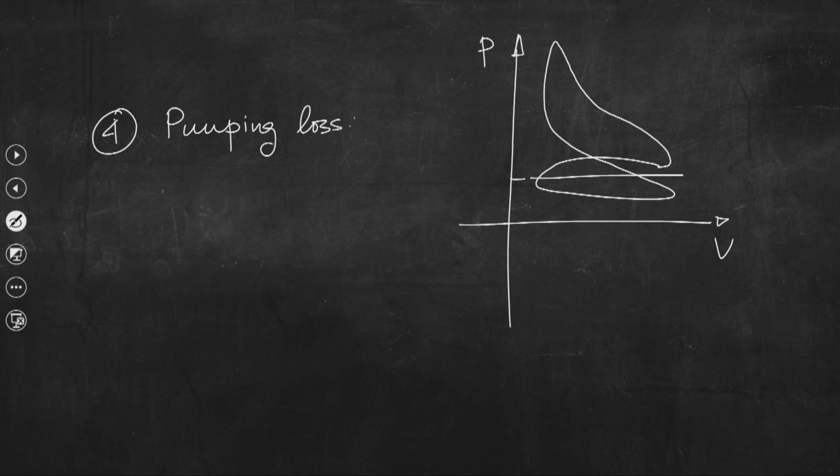So, you can understand, this is called positive work and this is negative work. This negative work is essentially blowdown work. Now, the cycle absorbs energy, or absorbs work, during this part of the cycle, and this is called pump work. So, if I write here, this absorbs energy, certainly energy in the form of work, from the engine.